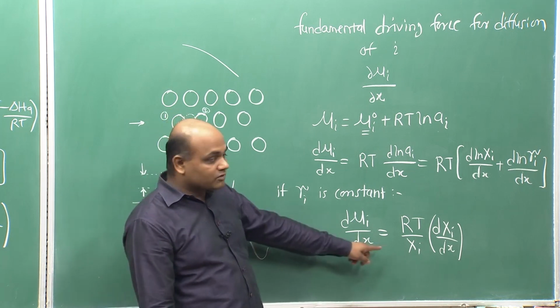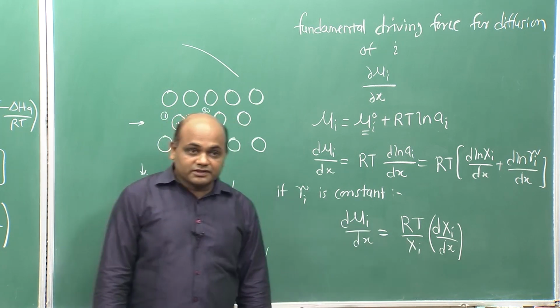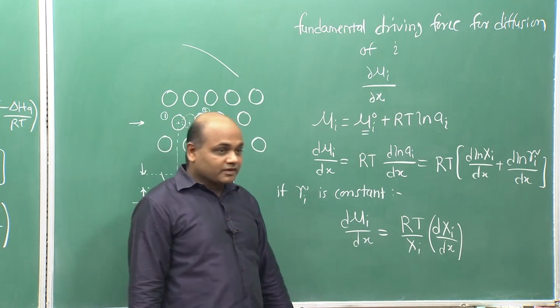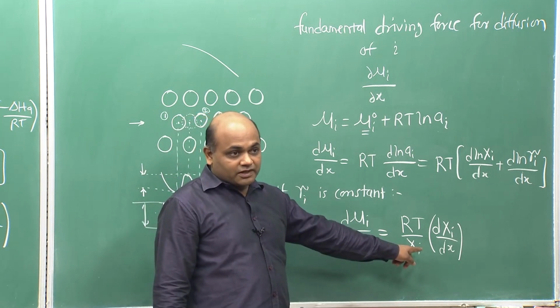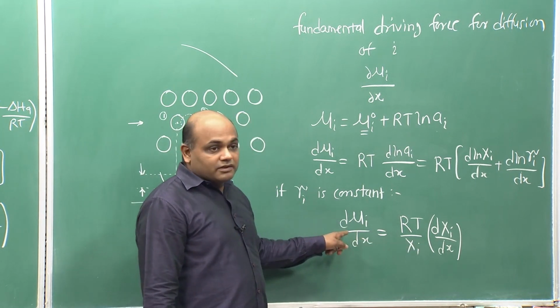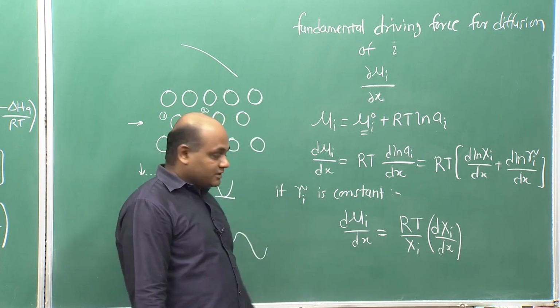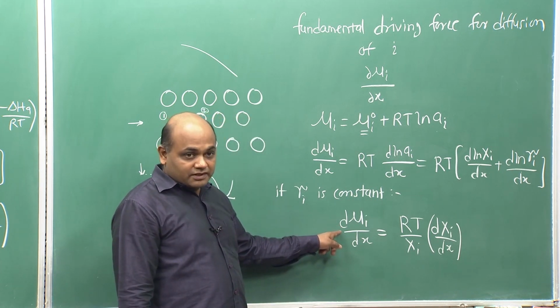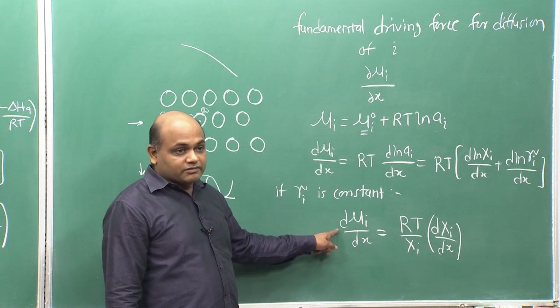Once you know the diffusion quantities in terms of concentration gradients treated as driving force, you can convert them back into the diffusion quantities when we treat chemical potential as driving force.